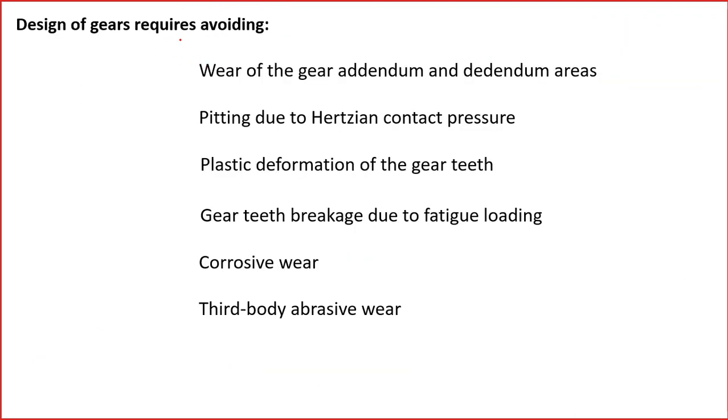So design of gears requires avoiding the wear of the gear addendum and dedendum areas. So this is very important. Pitting, avoiding pitting due to Hertzian contact pressure or stress. So pitting can happen both during the sliding as well as during the rolling part. Plastic deformation of gear teeth. So if the material is not suitable and the stress is extremely high, there will be a gross plastic deformation of the gear teeth, and that will lead to adhesion and failure.